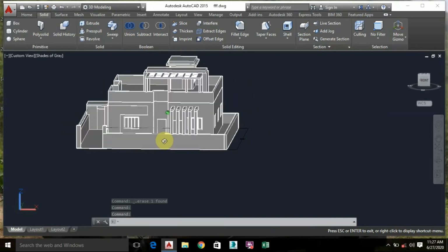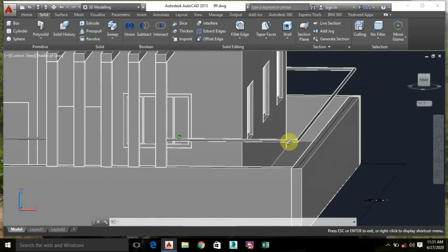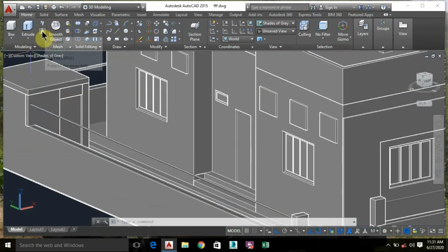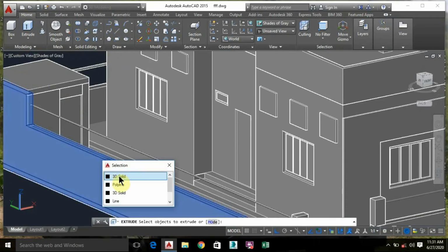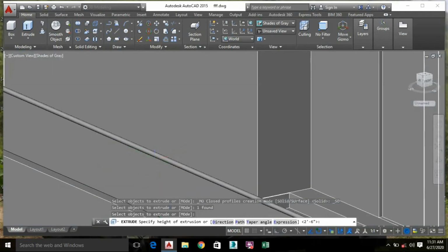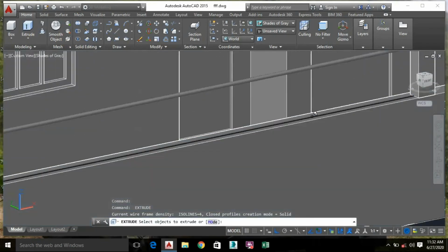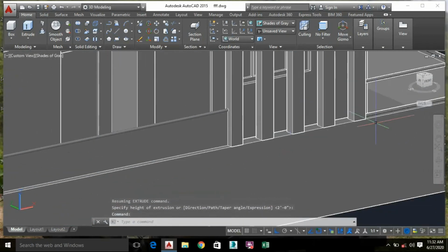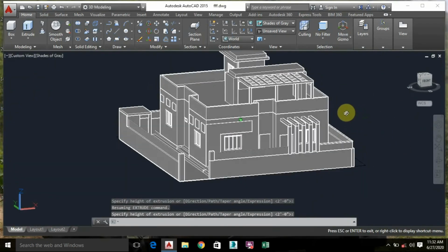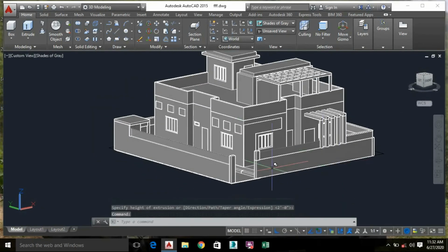So to modify our railings, I will use some boxes. First of all, I will create the railings in this way for this side also, for the back side of my house. Okay, now I will modify these railings. So I will make a glass here, so I will extrude that polyline which we have created to make the railings, extrude it up to the railing, and similarly for this face also up to this point, and then afterwards we will give the glass material to it.